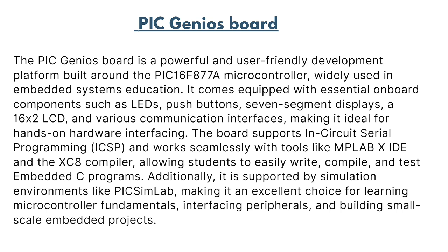PIC board. The PIC board is a powerful and user-friendly development platform built around the PIC16F877A microcontroller that is widely used in embedded systems education. It comes equipped with essential onboard components such as LEDs, push buttons, 7-segment displays, a 16x2 LCD that can be converted into 16x4, and various communication interfaces, making it ideal for hands-on hardware interfacing.